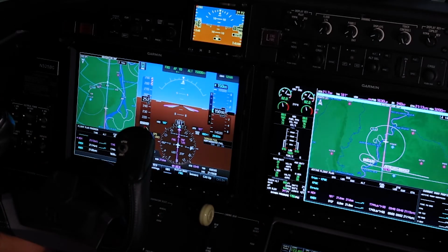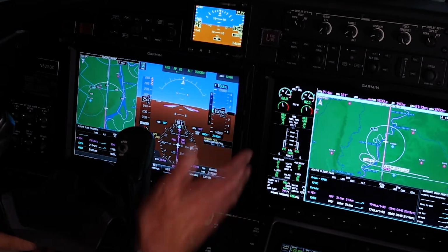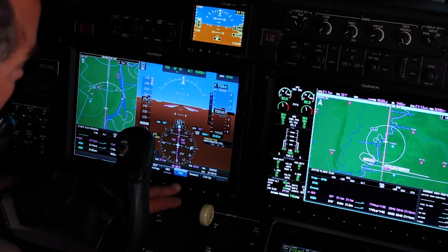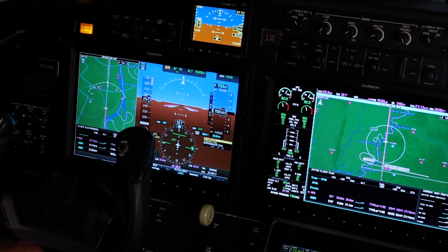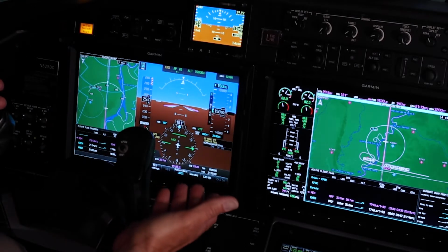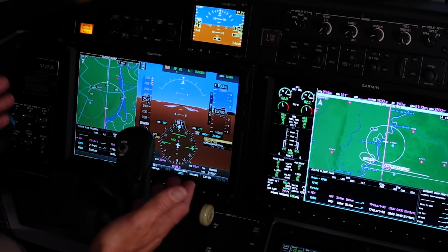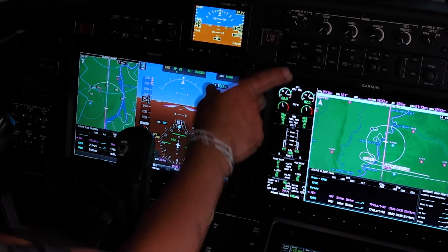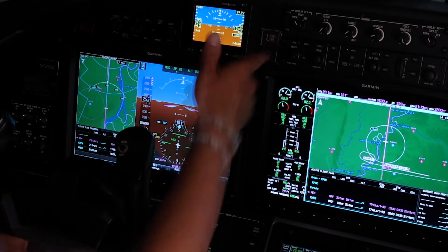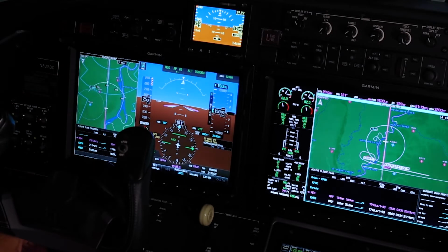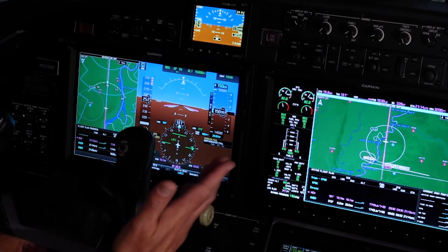So in this case, we still see that the FMS is navigating, but if it wasn't and we needed to navigate to the VOR using the VHF signal, we of course first have to switch our CDI source. The Garmin is telling us it doesn't like that. We've changed our nav source while we were tracking in nav mode. So this is one great reason to always fly with your heading bug synced. It's just one button push to put yourself in heading mode. The autopilot's not going to do anything unexpected.